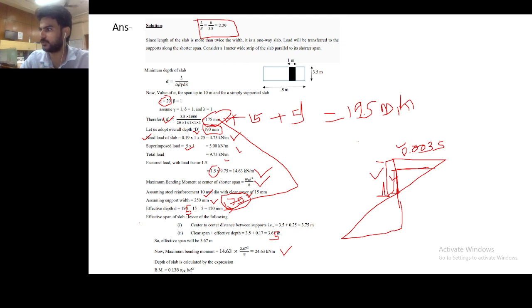That's why it should be equal or greater. So MR should always be greater than the bending moment coming onto our beam. For safety purposes we take the bending moment equal to the moment of resistance, and by equating them we can solve the problems. If it is greater, it's always good. Thank you, sir. Okay, I will relook at the working stress method and let you know.